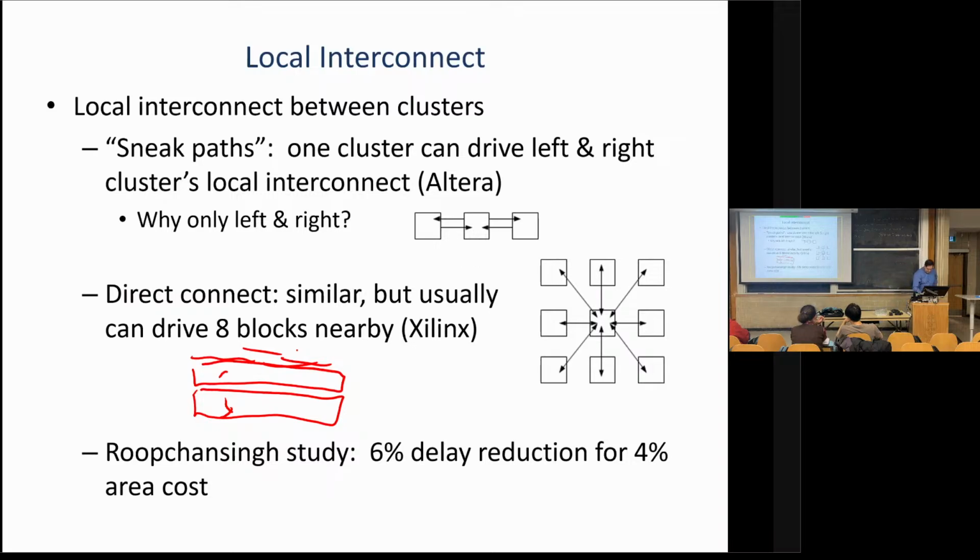And the vertical routing, if you think that the chip has length 4 vertical wires, it doesn't really. What it really has is length 5 vertical wires, okay? So every wire can actually reach one longer than Quartus would ever tell you, which means if there's one broken row, it still reaches past it. And basically the programming hardware can shift the bit stream, and the chip will be programmed with up to 4 broken rows. They can't all be on top of each other. Basically, each broken row protects you. Basically, for every 25 rows, you make one spare one typically, and you can handle up to 1 defect in those 25 rows. And it's invisible to the end user.